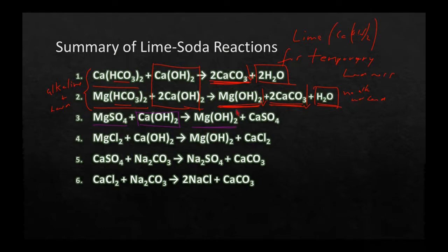In this reaction, it produces a magnesium hydroxide flock and calcium sulfate, which is the same as this stuff here. So yes, we've precipitated the magnesium, but all we've done is converted this type of permanent hardness into another type of permanent hardness. So it's kind of like a wash, right? You go, well, why do we even bother?